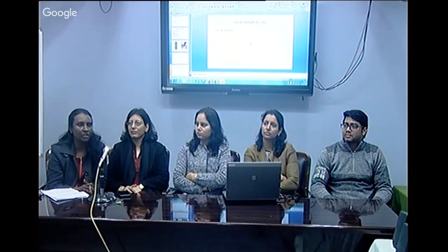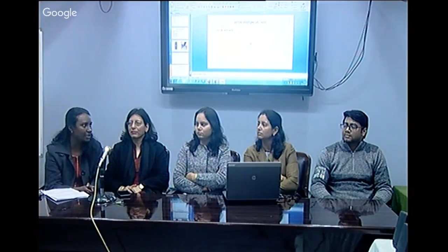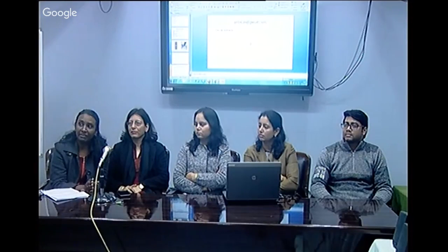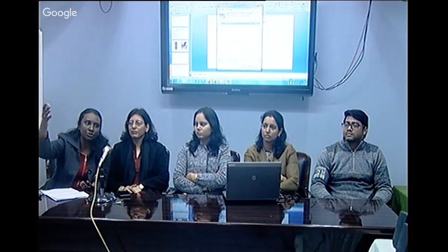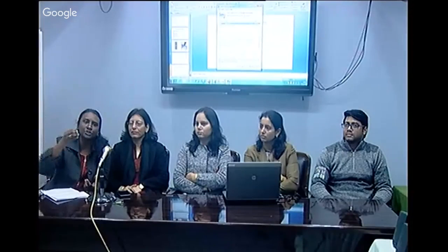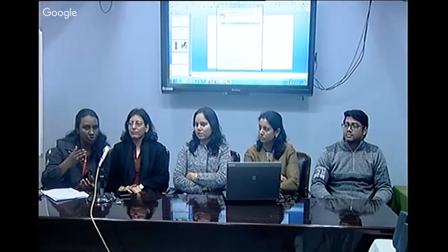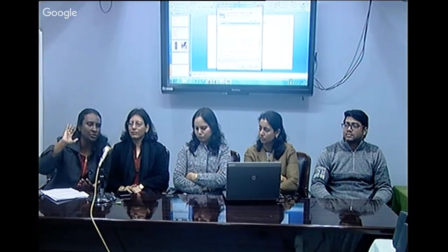Yes, ma'am. Really, it can be used even for PhD or MTech. You can see Sandeep, today he was delivering a lecture on the Mega, I think. His research work was on a 5-level multilevel inverter, three-phase. There also, Arduino is just a controller. Your power system is the power circuit. In order to interface the two, you have the power circuit and the control circuit. In between, as I already told you, you require optocouplers or driver ICs. So it gets isolated, and the control circuit has nothing to do with the power circuit.